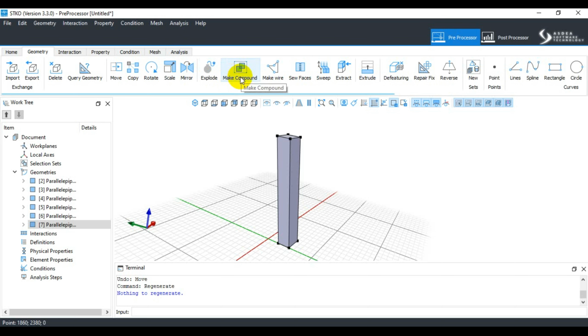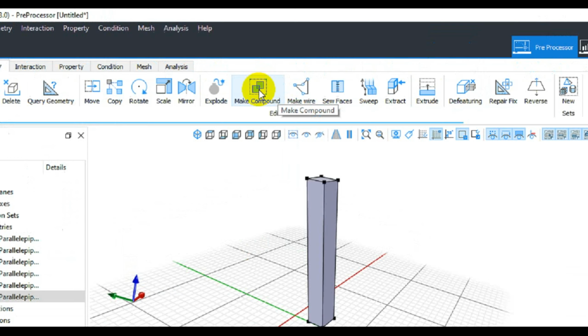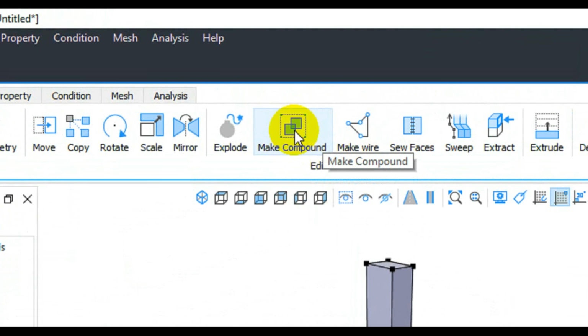Related to the explode command is its opposite, which takes all those features which are exploded and makes them a combined model. If you are using Abaqus software and have a composite structure, we tie them together with the merge command in the assembly module.